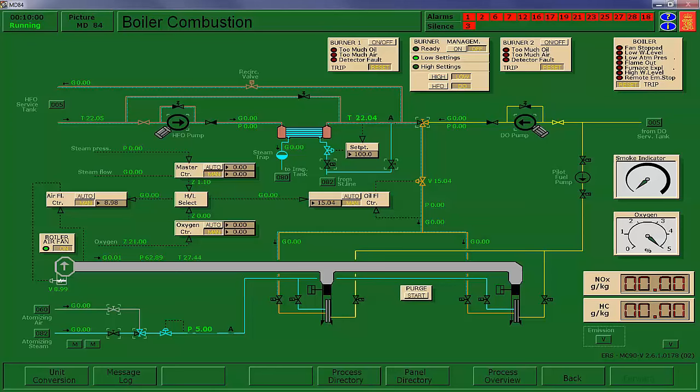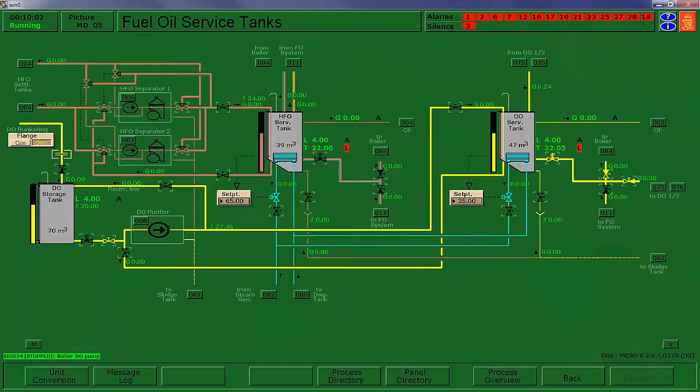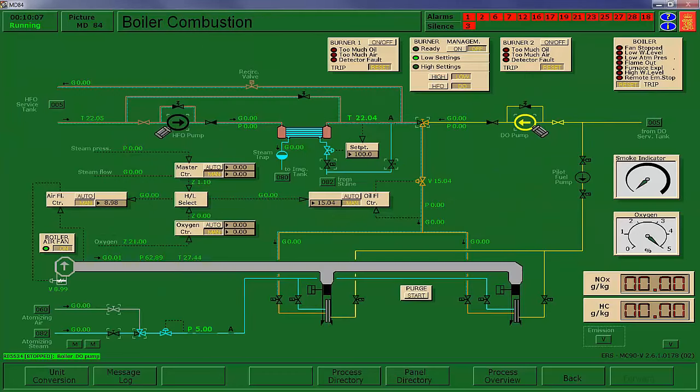But anyway, we'll go ahead and start our diesel oil pump up. I did open up the fuel. So we'll go ahead and start that up. I've got 15% on my fuel oil regulating valve, about 9% on my forced draft fan damper. That should light. The pilot comes on and ignites the pilot flame, and then you'll see the main valve open and ignite the main fire, and then this will go out again.